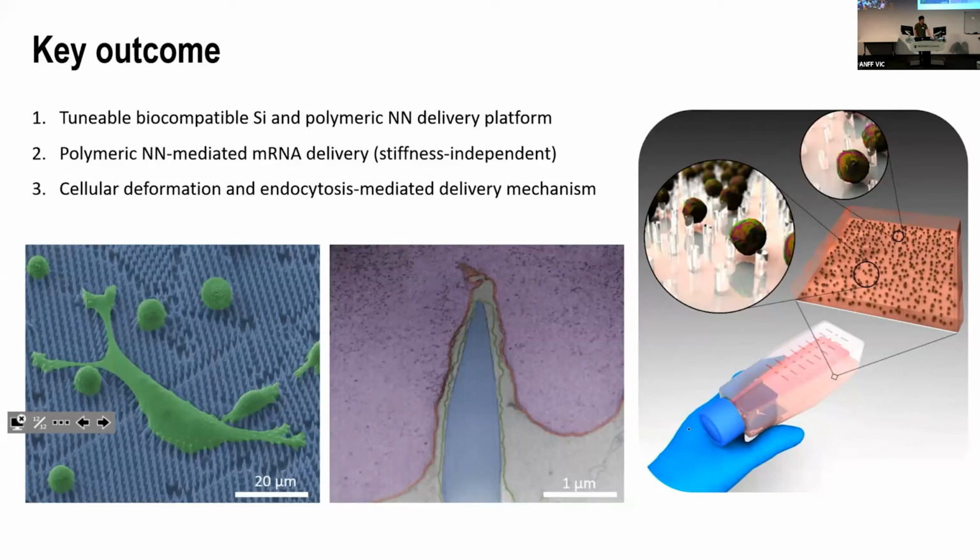Thanks, HaoZhe. There's a couple of questions from Ravi. How were the silicon pillars sharpened? What are the process steps involved? The nanoneedles can be further sharpened by using the same deep reactive ion etching process, using the pseudo-Bosch process with a mixed gas. That can further sharpen the tip of the nanoneedles if it's not sharp enough.